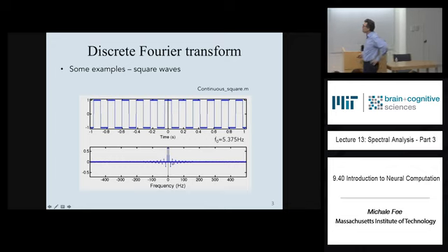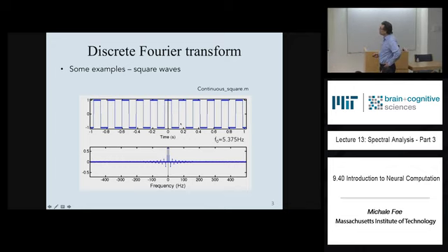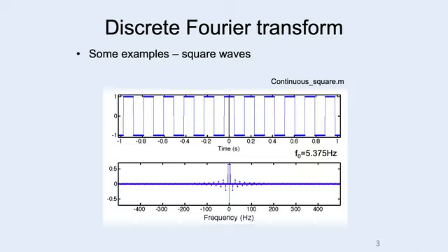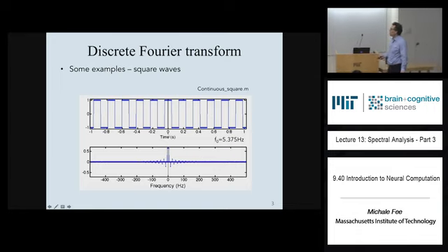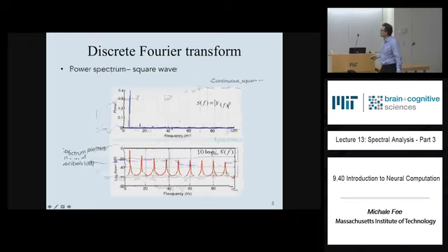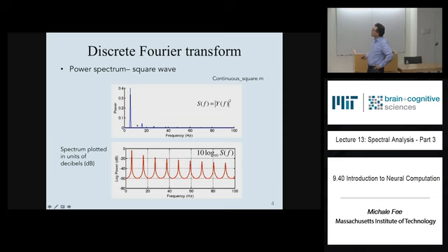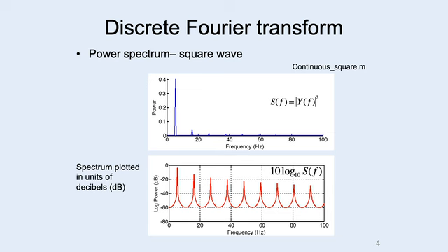We also discussed how you can compute the power spectrum of a signal from the Fourier transform. So here I've taken the Fourier transform of this square wave, and now we take the square magnitude of each of these values, and we just plot the square magnitude of just the positive frequency components. For real valued functions, the power spectrum is symmetric. The power at each of these frequencies for the positive frequencies is exactly the same as the power in the negative frequencies. So if we plot the power spectrum of that square wave, we can see that there are multiple peaks at